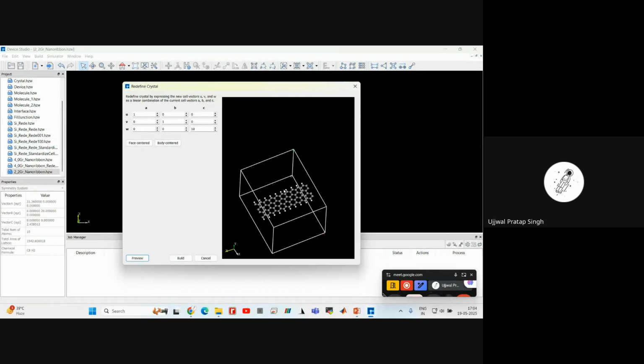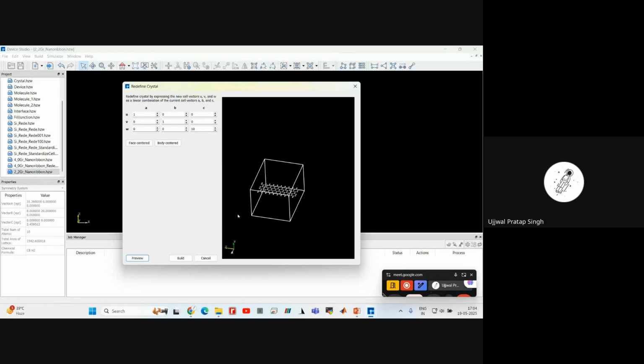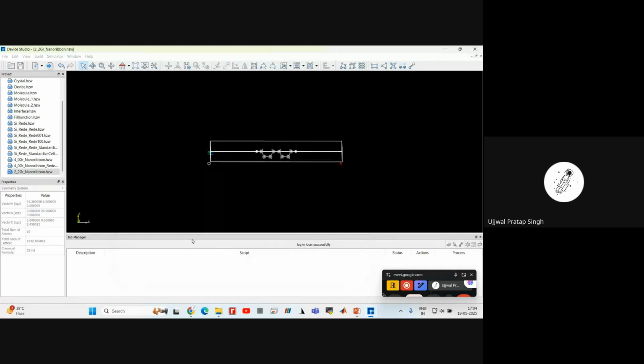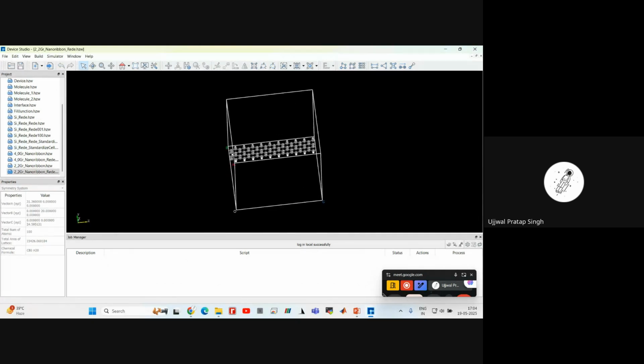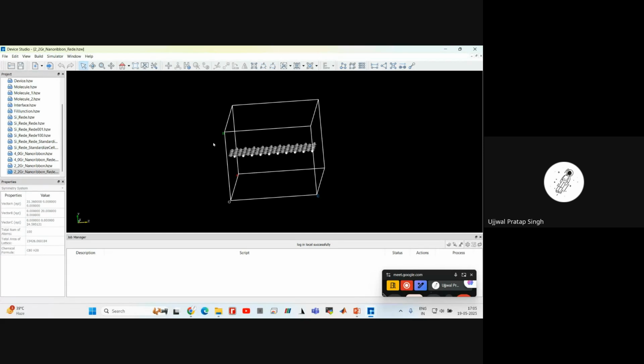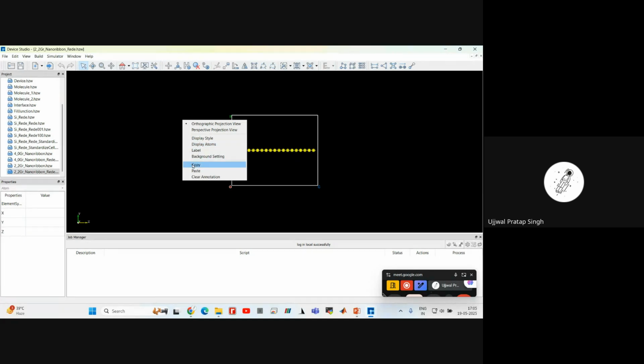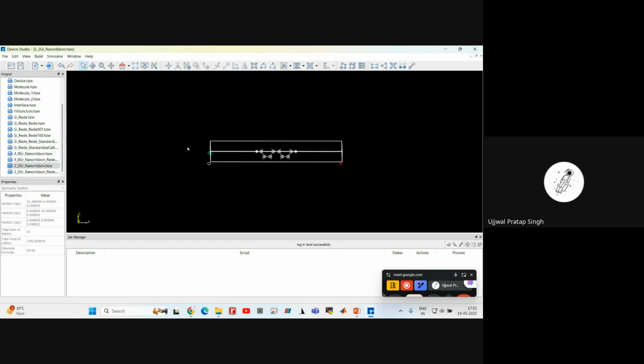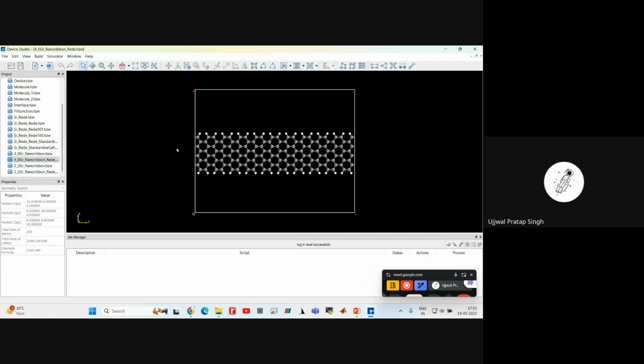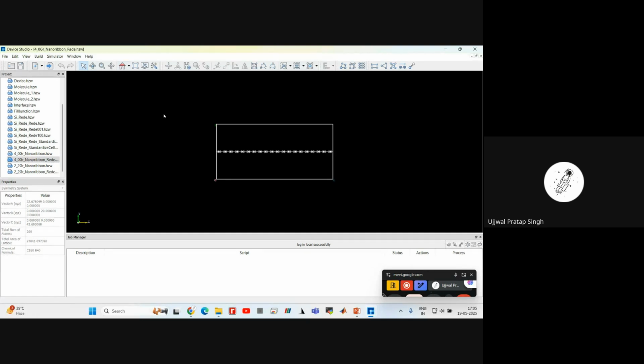And see, again build. You can also left click of the mouse and drag and select all atoms. And right click of the mouse, you can see the copy option. Copy this and move to the armchair graphene. This one. And paste here the zigzag graphene.